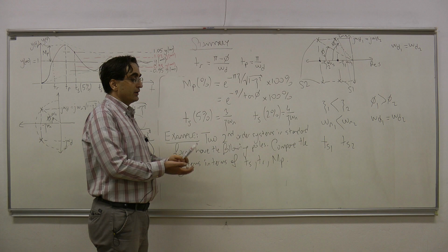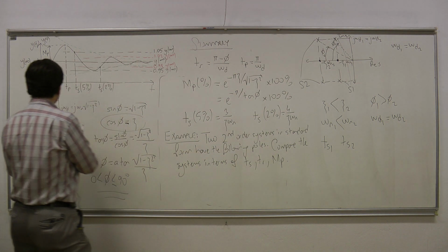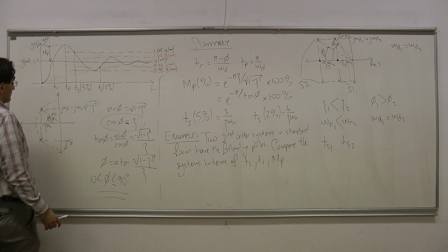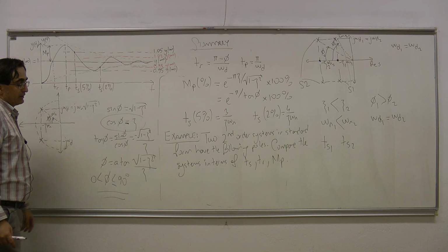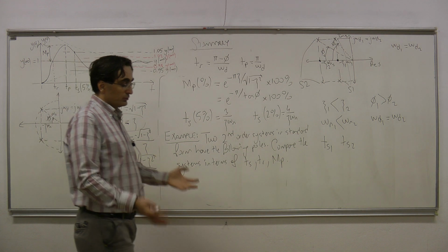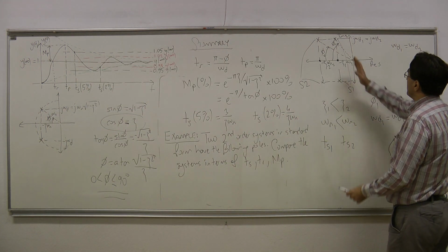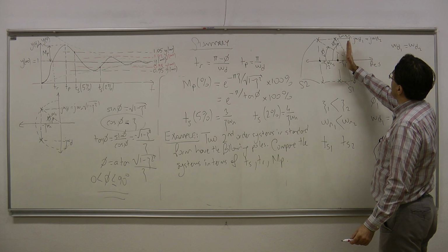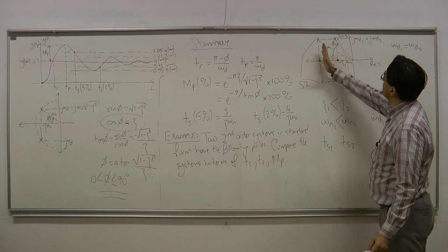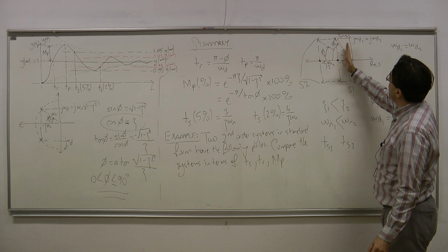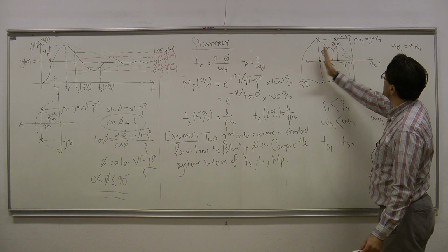If the real part is large in magnitude, then the settling time is small. If the real part is small in magnitude, then the settling time is large. So as the poles go from right to the left, the settling time would decrease, because the poles are getting further away from the imaginary axis.